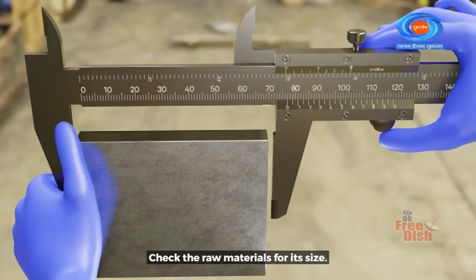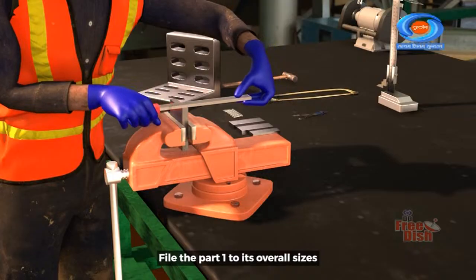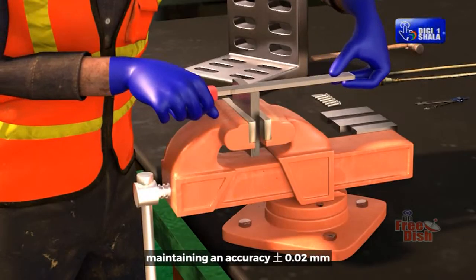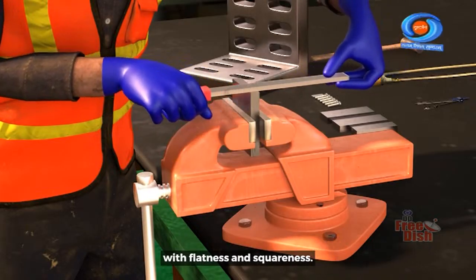Check the raw materials for its size. Next, we are going to file all the parts. File part 1 to its overall sizes, maintaining an accuracy plus or minus 0.02 mm with flatness and squareness.